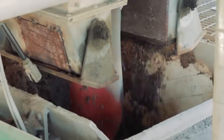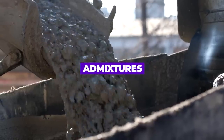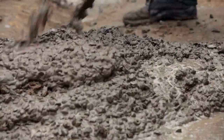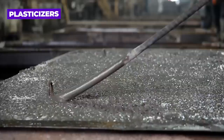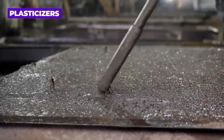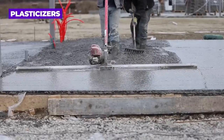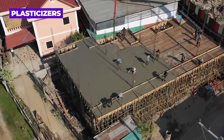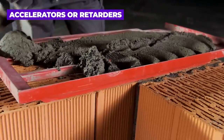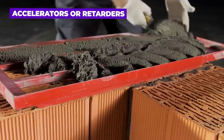Now is a great time to talk about the hidden stars of concrete manufacture, the admixtures. These chemicals offer a range of advantages and may be added to concrete to improve its properties. Plasticizers give the concrete greater workability, which refers to its ability to be easily molded and placed without segregation or excessive bleeding of water, allowing it to reach congested areas. Accelerators or retarders are another type of admixture that fasten or slow down the setting time for concrete.